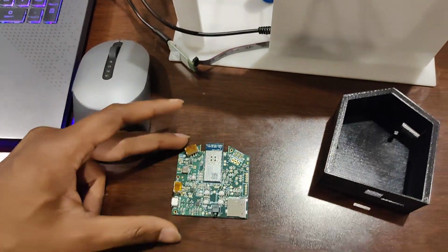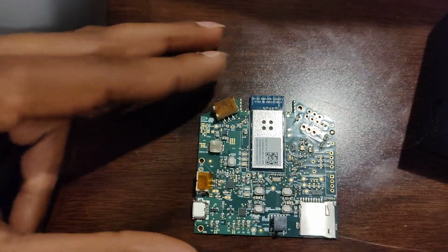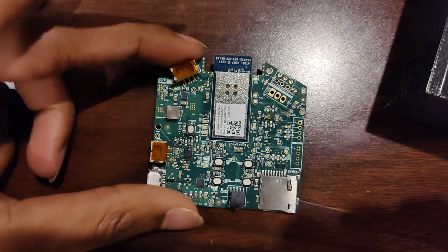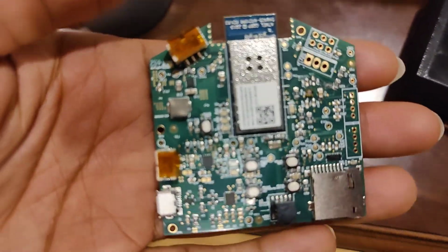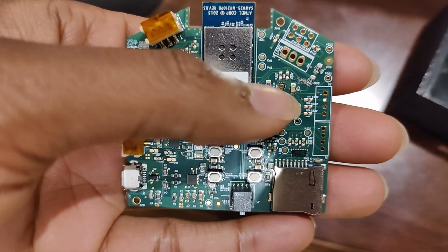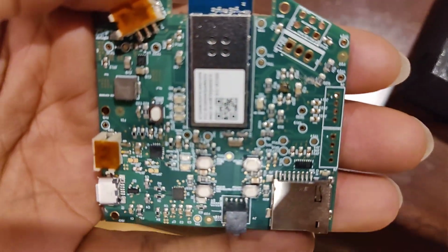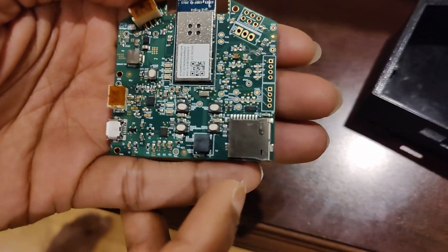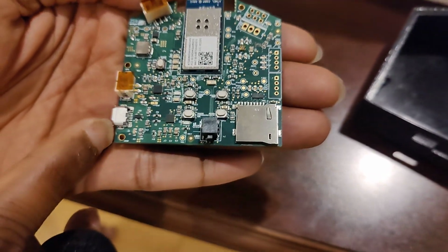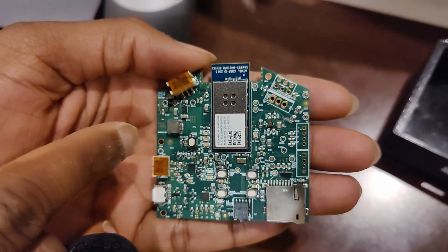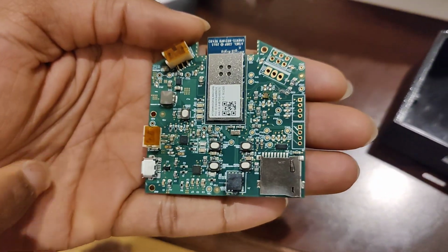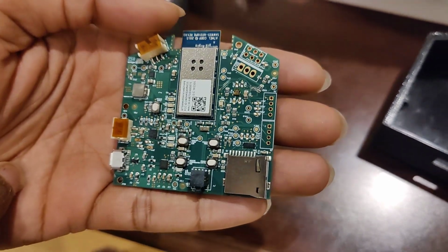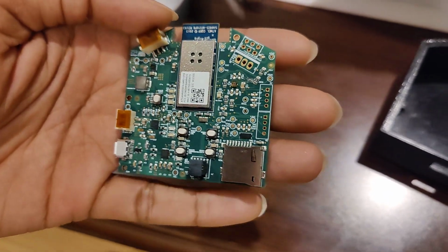And now this is the PCB. This is the actual PCB, which resembles the shape of a house, indicating our AirLight project. If you look at this PCB closely, we have an onboard ambient light sensor on the top right, and other components like the microcontroller, an SD card module, and a power module. We are using a 3V3 buck, so the 3.3 volts will be used to power all the sensors, actuators, and the working of other components.